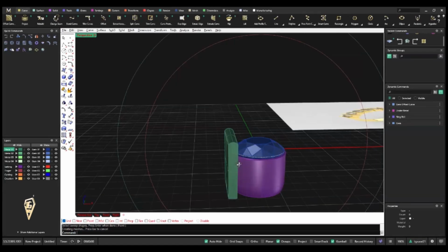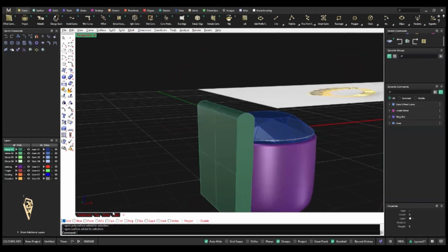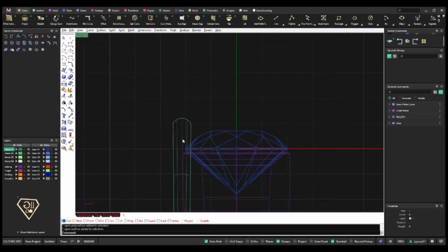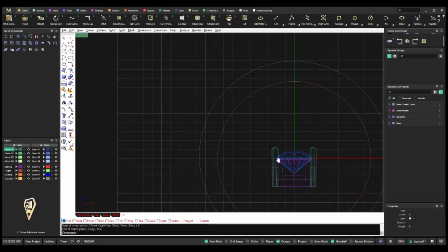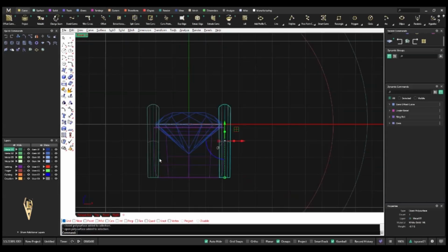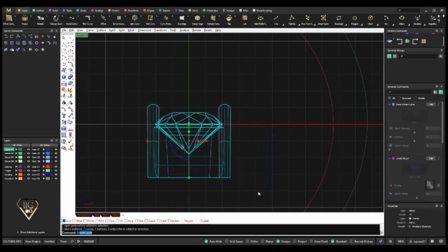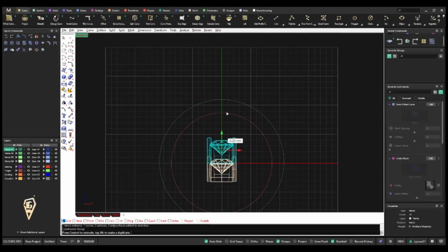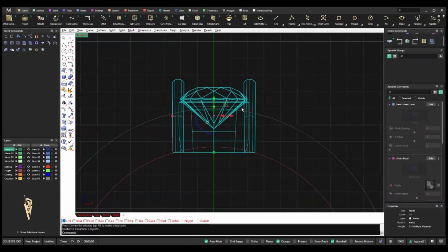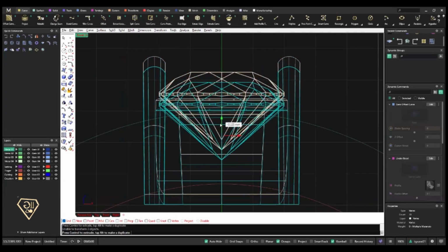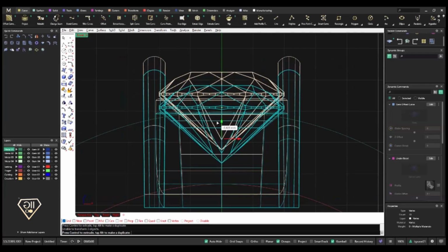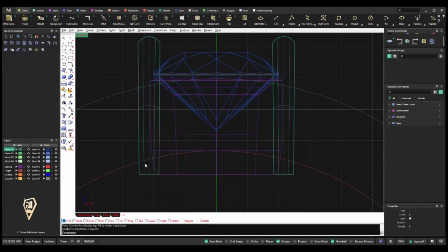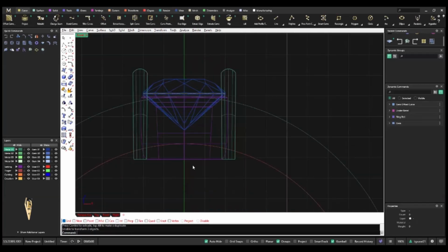Okay, this is not compulsory, but if you want to try something new, you can change this thing. Okay, once we have done this thing, still if over here, if you can see, we'll go in front, we'll select this thing and we will mirror this on the opposite side like this. Okay, once we have got the three parts over here, now we can box select the whole thing and group this thing till that part, enter, and in front itself we'll move this thing up like this. Now the main thing is the gem over here, it should be somewhat like this, should come like this. Okay, now this part is coming inside the ring rail. Okay, that we will see in the last part. So what we'll do is basically delete those things.